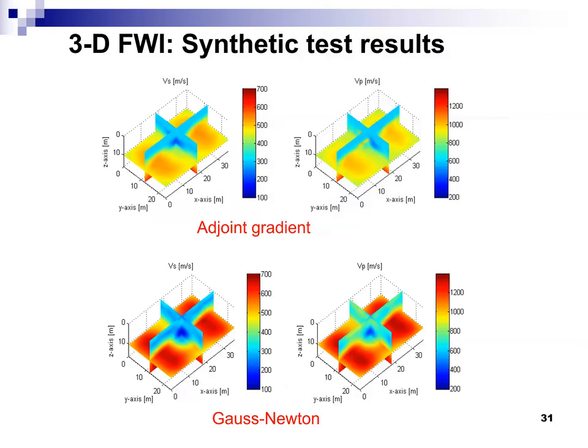Here's the result. Adjoint gradient method, and then Gauss-Newton at the bottom. So for adjoint, we see the soil layer on the top, rock at the bottom, and a low velocity zone here. We do see something from the adjoint, but it's not as clear as Gauss-Newton. You see the Gauss-Newton right here, and the velocity goes very low. So it's a clearer image because Gauss-Newton focuses on the void.